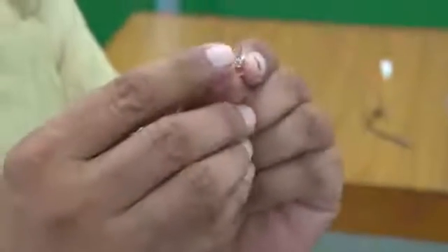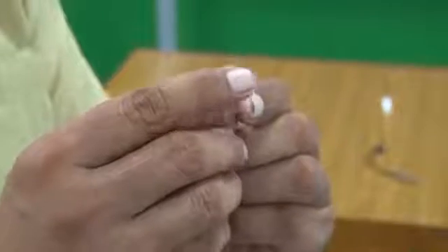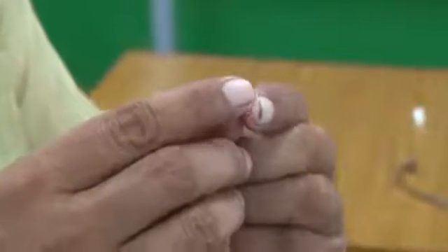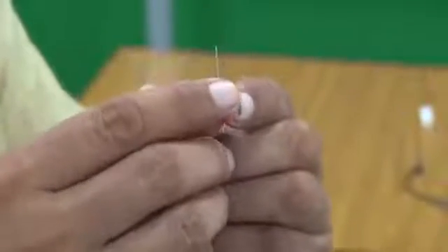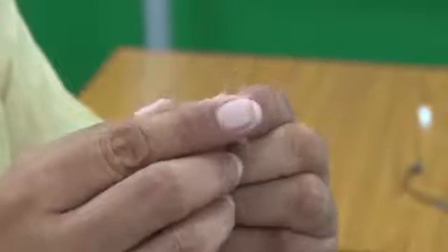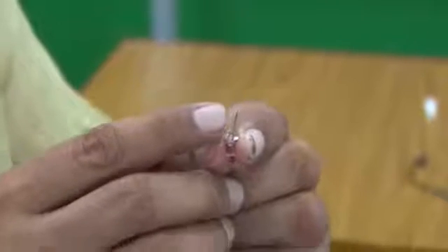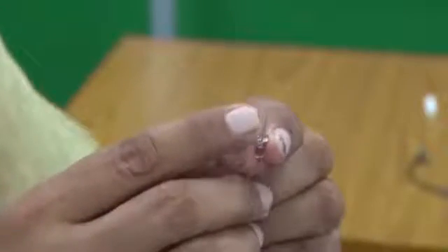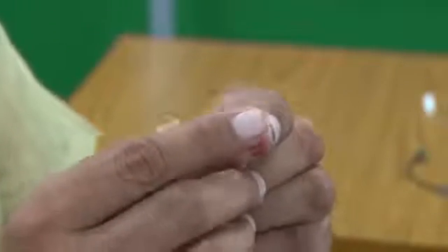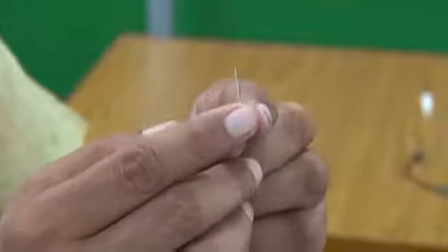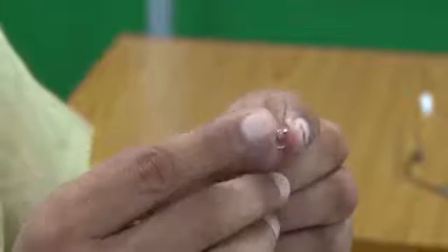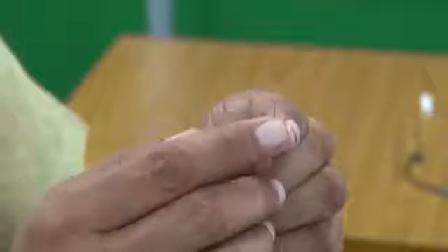As you can see, the sizes of these two are different. One is shorter, one is longer. This is to tell that the longer one is to be connected to the higher voltage side, and this one to the lower voltage side, for forward biasing. So, this is the P side and this is the N side. Let us connect this, supply some voltage and see what happens.